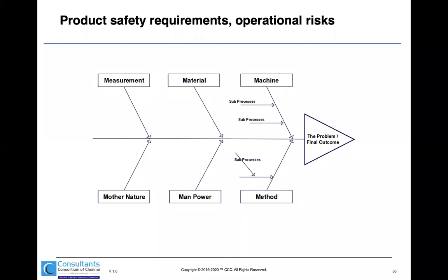So what can go wrong with respect to man? For example, competency, personnel certification, motivation of the employee, human factors, right? That is very critical in AS9100, the entire AS series of standards. Their psychological aspect, their attitude, right? Then machine-specific considerations, like the program: who has control of the CNC program? Can the operator modify the programs, or can only authorized people do that, right? What type of maintenance mechanism do we have on the machine? Those we can consider.